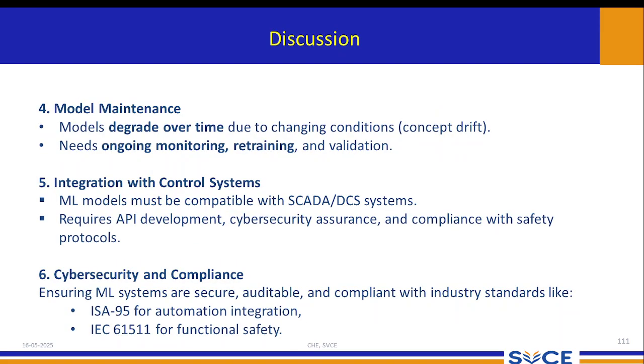And coming to the other three subdivisions: model maintenance, integration with the control system, and cyber security and compliance. Under model maintenance, models degrade over time due to changing conditions and concept drift, and need ongoing monitoring, retraining and validation. Integration with the control system: machine learning models must be compatible with the SCADA or DCS, the distributed control system, through which the control room finds out whether the process is going right or not. Otherwise, the system will not be able to understand the model's input.